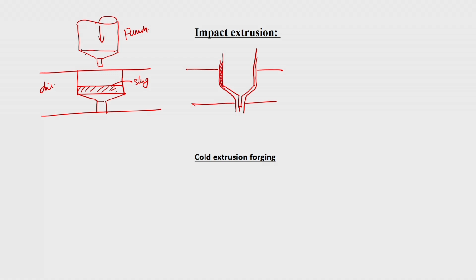This is your extrudate. It will just move backward in this direction, because once the punch is entering perfectly, it is matching now, so metal will not extrude into this portion. Rather, it will extrude back. Initially some extrusion will be there, and this is that part, like the toothpaste opening, the mouth opening.